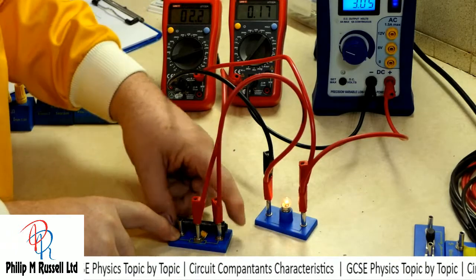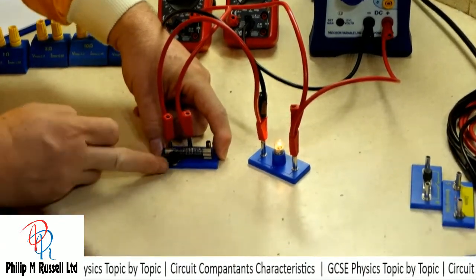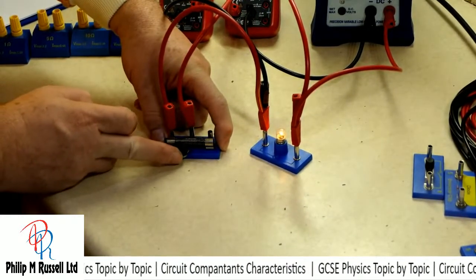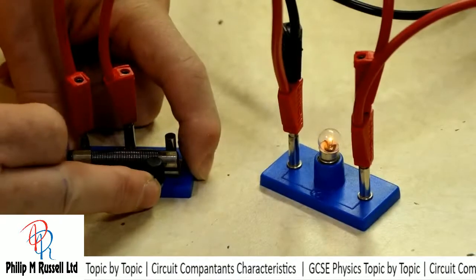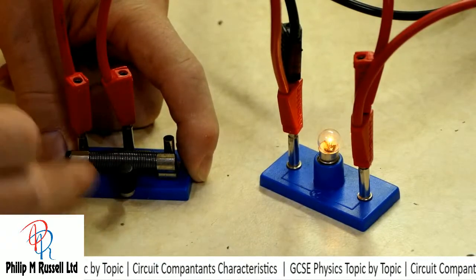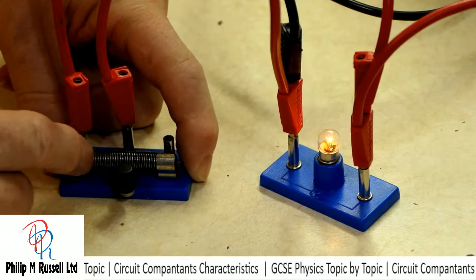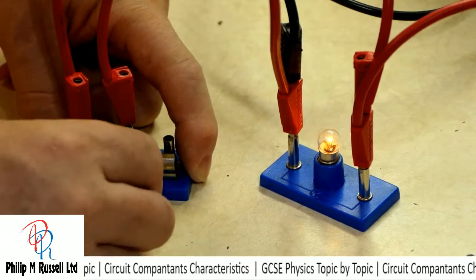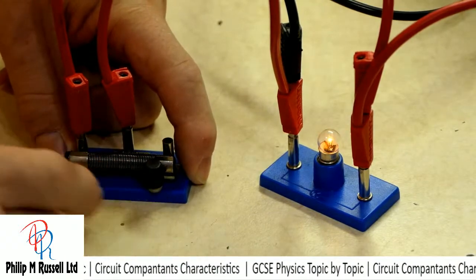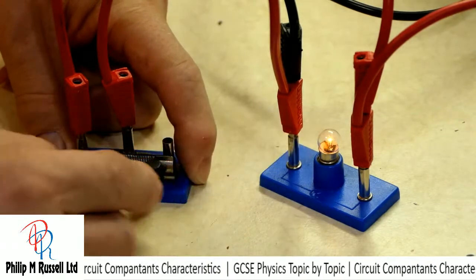Just moving this handle, and move it that way if that helps you to see. The electricity is coming in here through this metal bar onto this coil, and the electricity then flows along there and out. So if the resistor is larger, we're going through more of the coils, and the bulb is dimmer.